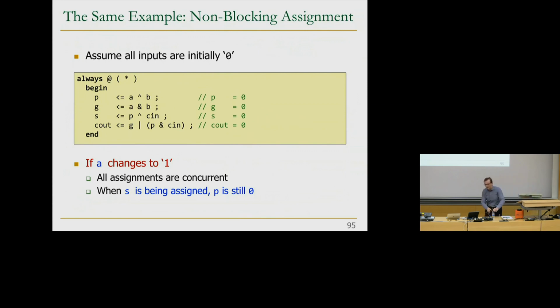Yes? When you say they are executed concurrently, could it be that the statement that executes concurrently will get translated into components which are slower compared to the other ones, and then the new value has already been assigned? We'll talk about timing later, but a good synthesis tool should not do that in this case. Basically, it should ensure that these are done at the end. But yes, there could be dangers over here. Let's talk about timing tomorrow. So logically, all of the values should be changed at the end.